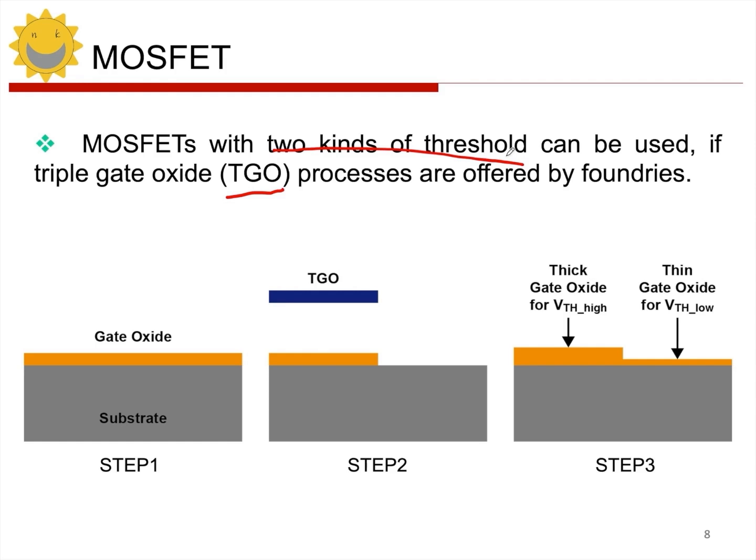So, for low threshold devices, their dimensions can also be quite small, and their operating voltage can be low. The main benefit of this is that it can save power. Secondly, it can reduce the area. So, for digital circuits, they will often use these low threshold devices. But it's different for analog circuits. For analog circuits, they prefer devices with better intrinsic characteristics, right?